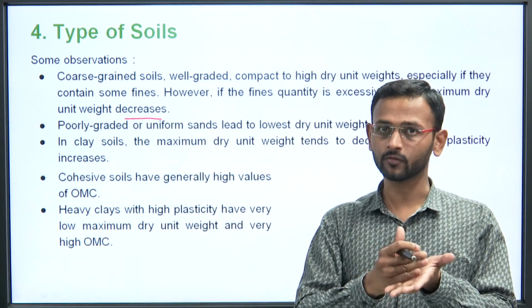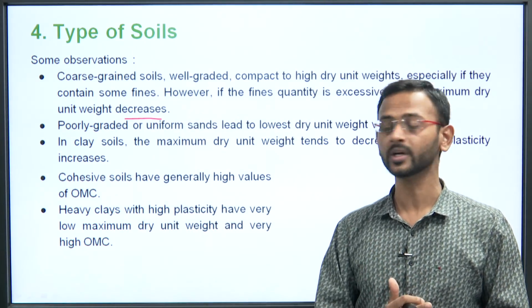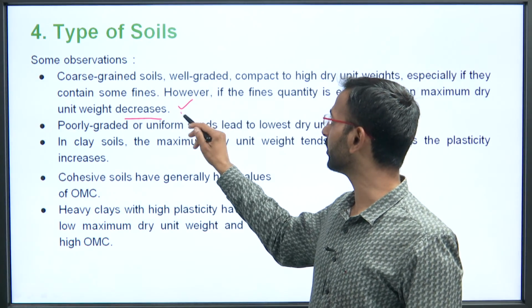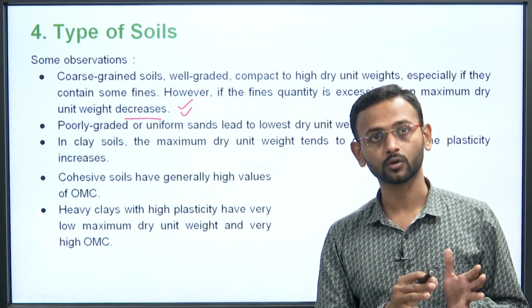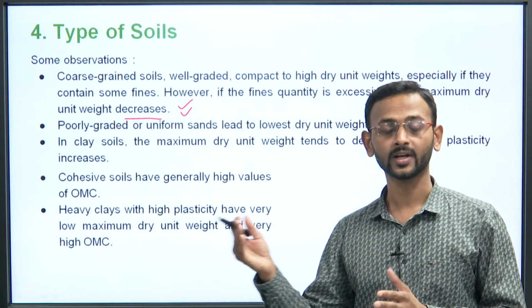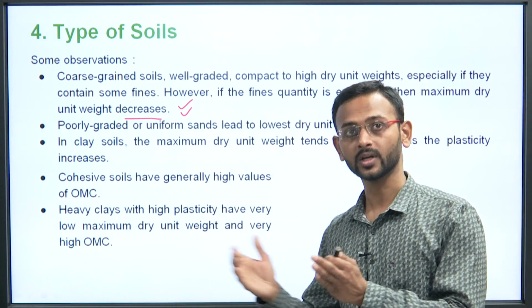So for a certain amount of fines it is okay, but later on the maximum dry unit weight will be decreasing. That will not be very beneficial for us, because in the field we try to find out what will be the maximum dry unit weight that can be achieved, because that will be making the soil more and more stable.